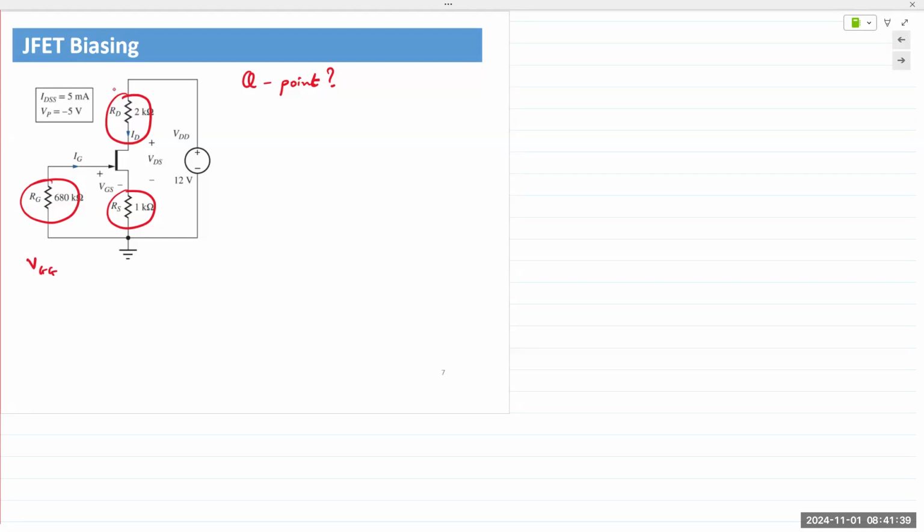And we'll obtain a set of curves where for every value of VGS that you apply in the lab, you increase VDS from 0 to a positive value. So right now here, we don't have any source on the gate, which makes our job easier. So what we want is ID, the drain current. We want VDS, the drain-to-source voltage. And of course, we also want VGS.